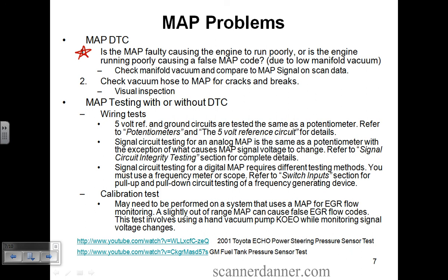This car that we have in here, this Buick Century, and I haven't edited the video that we shot yesterday with the plugged up cat and the BAT02 sensor. Plugged up cat is going to affect intake manifold pressure, wouldn't you think? That's why the car won't run. Exhaust valve opens, we try to force this gas out and we can't get rid of it. So what happens? Exhaust valve closes, intake valve opens. Where does all that pressure go? Back in the intake. If this car had a map sensor, it doesn't, but if it did, we would have a map sensor trouble code on this car.